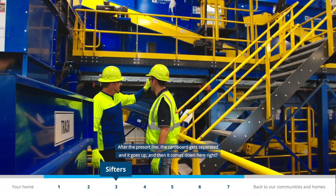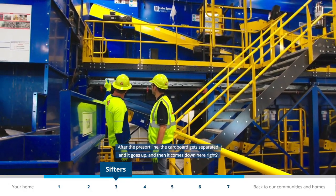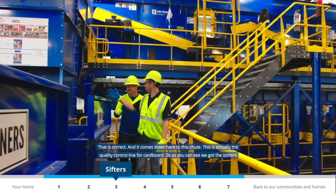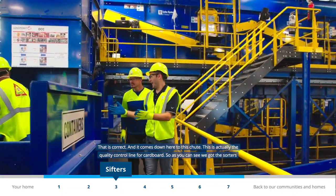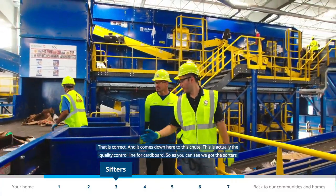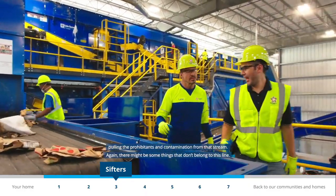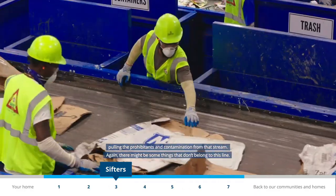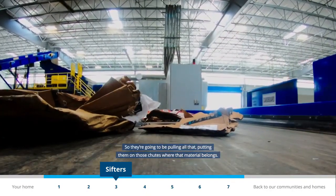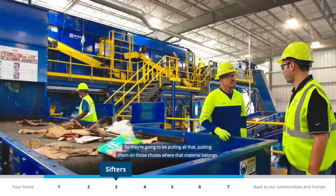After the pre-sort line, the cardboard gets separated, it goes up, and then it comes down here, right? That's correct. And it comes down here to this chute. This is actually the quality control line for cardboard. So as you can see, we got the sorter just pulling the prohibitives and contamination from that stream, because again, there might be some things that don't belong to this line. So they're going to be pulling all that, putting them on those chutes where that material belongs.